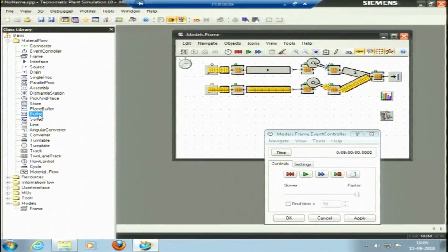The big buffer is placed between two plant components for certain purposes. It temporarily holds parts when the following components fail, when the successor is not able to receive the component. The second important function is that it passes the part on when the preceding components stop working. A buffer with large enough capacity for covering all failures leads to complete decoupling of the plant, and has other attributes as well.